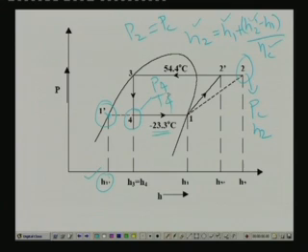So, if you are fixing the pressure, temperature is automatically fixed. That means pressure and temperature are not independent properties in the two phase region. So, specifying both is meaningless, or useless. So, you have to specify any one and another property. What is that other property?